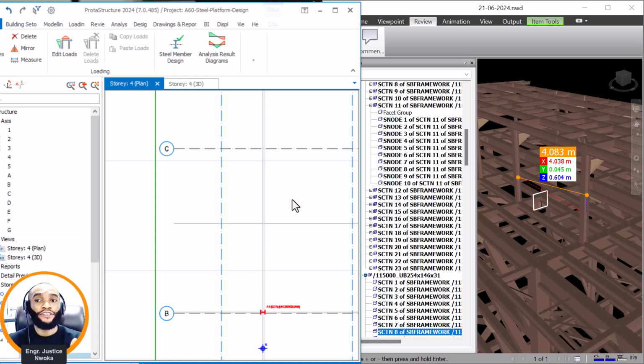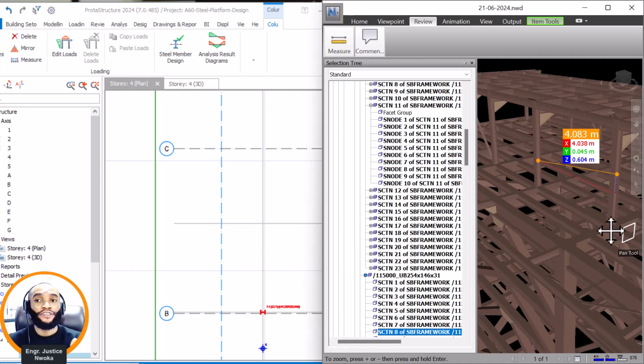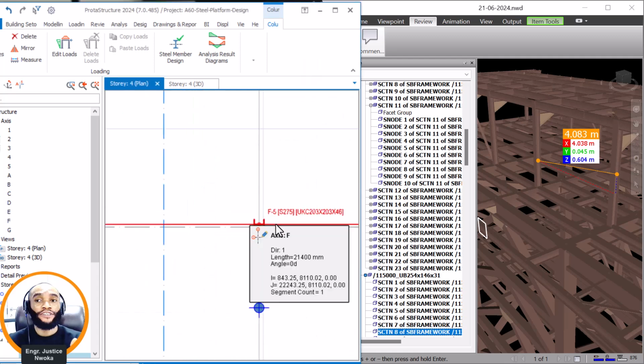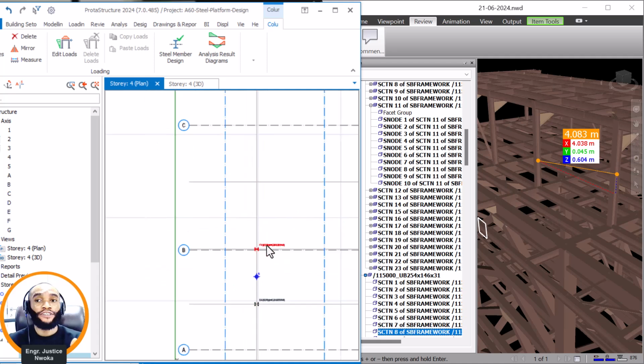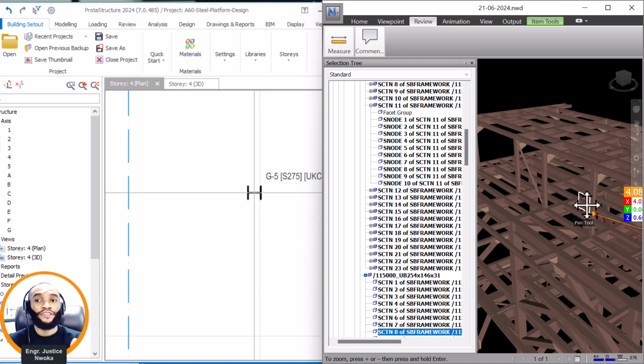So I'll click on this now, right click here, but we are going to have a steel beam first. You can see there's a steel beam carrying this thing. So we are going to establish that steel beam on the story 2, around the story 3 here. Don't forget, because you can see that there's a column still down here. So we are going to establish there's a support under it. But let's just establish these columns first, right? So put this right now and then establish this here. So we have the third column now being established, escape. Then we now have the other ones too.